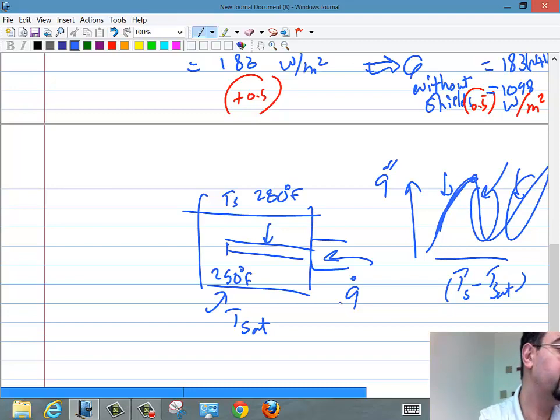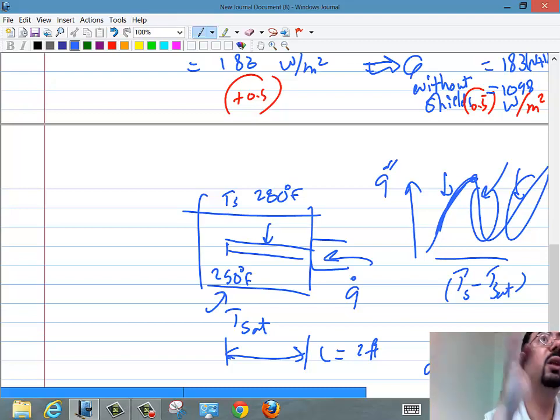All right? So we have the dimensions. L is given, it's 2 feet, and D is given, it's 0.25 inch, and it's a nickel plated heater. So we can get the CSF from that table. Remember, there is a table based on the material and the manufacturing technique. We can actually tell what that constant is. All right, and please find the rate of evaporation in pounds per hour. Assume steady state nucleate boiling.